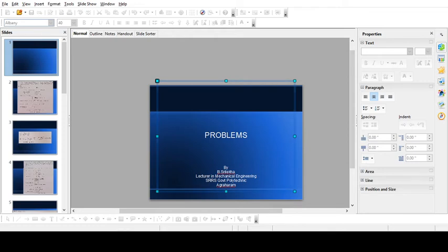Given that there are two stresses, one is along the x-axis, a tensile stress, sigma x, and its value is 50 Newton per mm square. So this will lead to an increase in the length and at the same time it will lead to compression along the y-axis. So it is extending in the x-axis means it will compress in the y-axis. Next, one more stress is there, that is 80 Newton per mm square. So this is compressing the width.